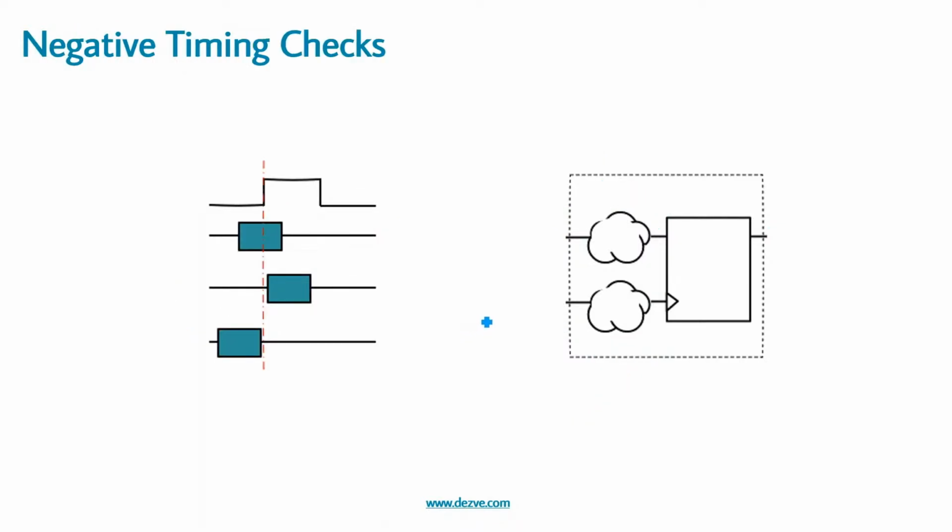Having analyzed the setup and hold requirement for this circuit previously, now let us see, we might have always heard, or even been asked in multiple interview questions, whether the timing checks can be negative: the setup can be negative, the hold can be negative. We know that setup and hold are just the checks with respect to the edge. Let us assume this is the standard cell from the library which has a setup and hold of 1, correct? Now this is fixed, correct?